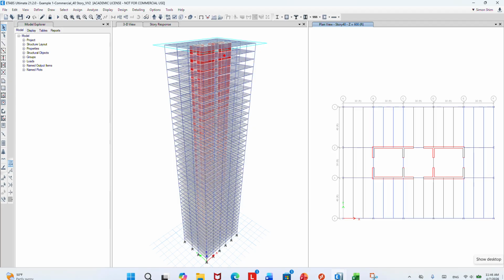Do we need 4? Do we need 2? It depends, obviously on the architectural program layout, but structurally, I'll consider 4 locations. 4 means your outrigger truss has a decent amount of sections we're gonna end up with. But if you're using 2, obviously much heavier sections we need to end up with, right? 4 versus 2.